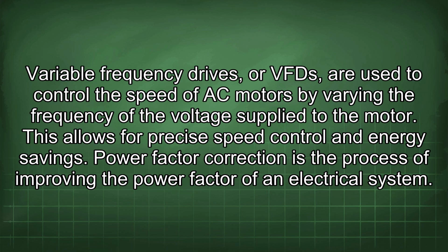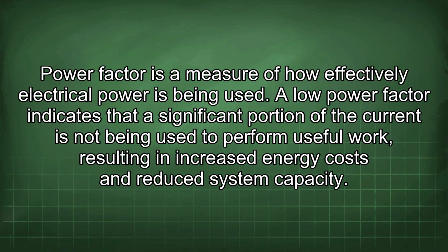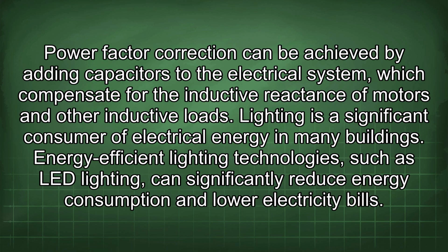Power factor correction is the process of improving the power factor of an electrical system. Power factor is a measure of how effectively electrical power is being used. A low power factor indicates that a significant portion of the current is not being used to perform useful work, resulting in increased energy costs and reduced system capacity. Power factor correction can be achieved by adding capacitors to the electrical system, which compensate for the inductive reactance of motors and other inductive loads.